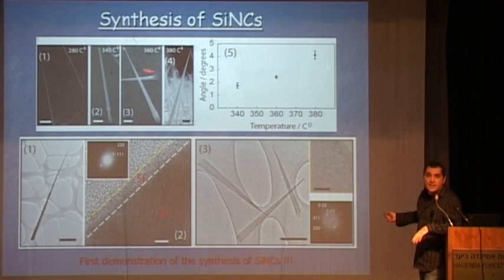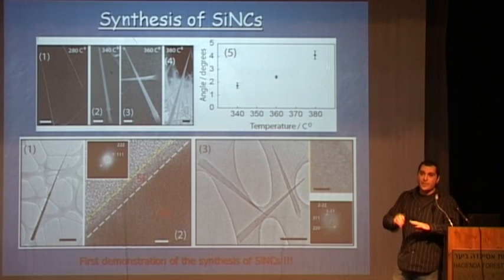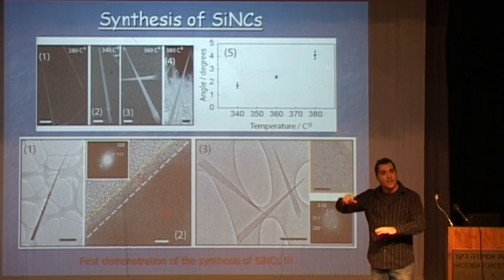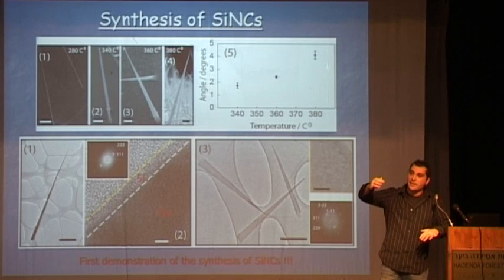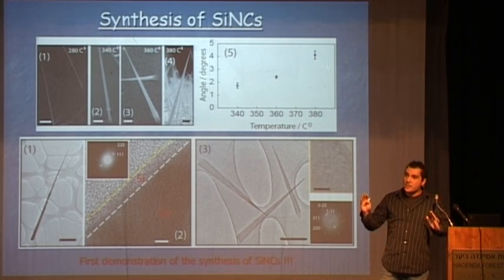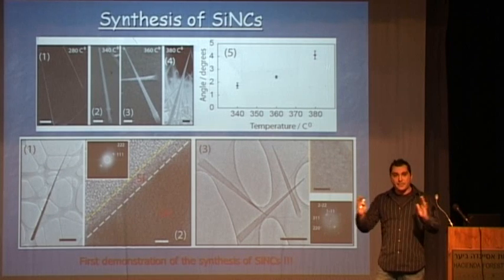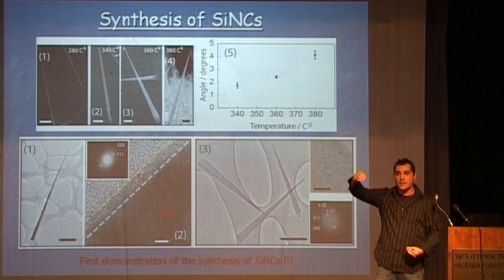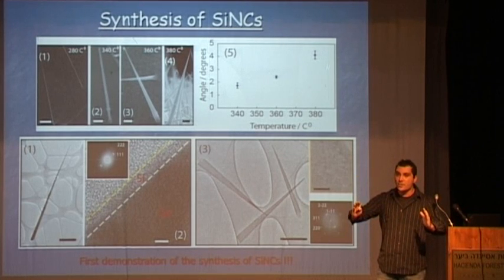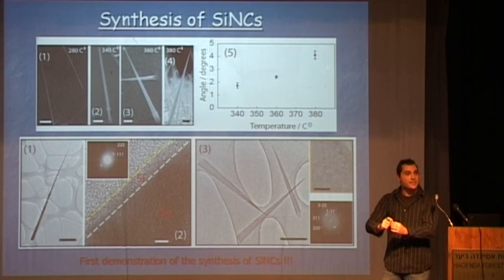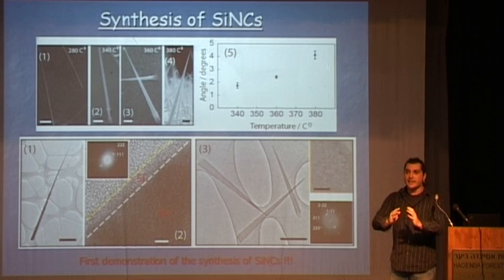But at higher temperatures, we have two processes. One process is the elongation of the nanowire, or what we call the axial growth, catalytic growth, coming only from the nanoparticle outside. And we have a second chemical process at higher temperatures, which is the pyrolytic decomposition of germane on the walls of the growing nanowire. So we have a radial enlargement of the nanowire and at the same time an elongation. So the areas of the nanowire which are exposed longer times in the setup get fatter and fatter and fatter.